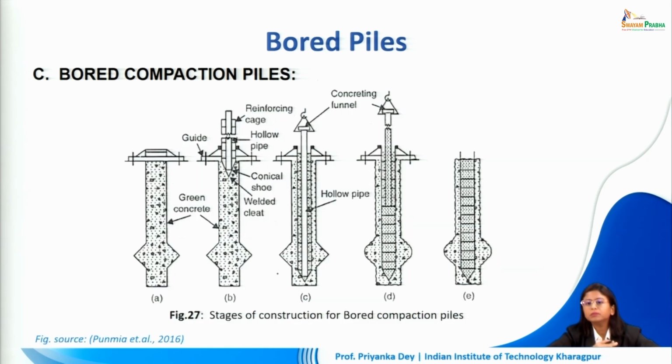So it is becoming a combination of driven and bored pile, because the initial process is boring, where then we are filling it up with concrete, and finally when that is done, we are driving in the reinforcement cage.